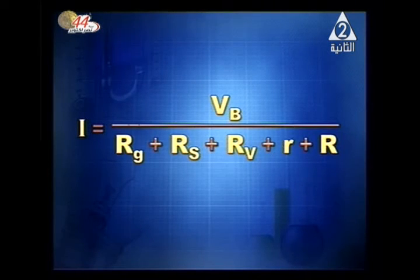When measuring an external resistance, the current, of course, will not be Ig. It will be less than Ig, and it is equal to Vb over Rg plus Rs plus Rv plus internal resistance r plus R required to be measured. Vb is the EMF of the cell, Rg is the resistance of the galvanometer, Rs is the fixed standard resistance, and Rv is the chosen value of the variable resistance. Internal resistance of the cell is denoted by small r. Resistance required to be measured is capital R.